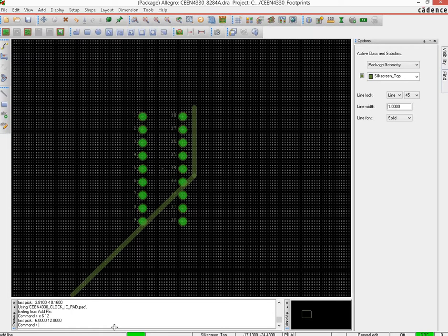I'll start at 6, 12, and then I'll go down. So that would be 6 minus 12, then minus 6 minus 12. Now here comes the important thing. I have to indicate that pin 1 is a little bit different, so I'll do that by changing the silk screen a little bit. I'll do minus 6, but then I'll not go to 12 itself, I'll go to 10.